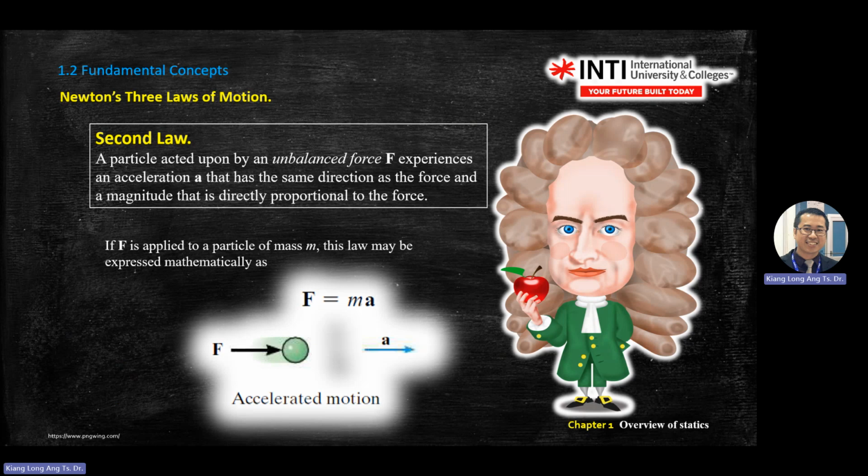Again, this module deals with constant velocity. So what happens to acceleration? It is 0. When this side is 0, the sum of all forces equals 0, and that is actually an equilibrium equation. It means you combine all the forces inside your free body diagram, set them equal to 0, and solve for the missing parameter. That is the idea for statics.